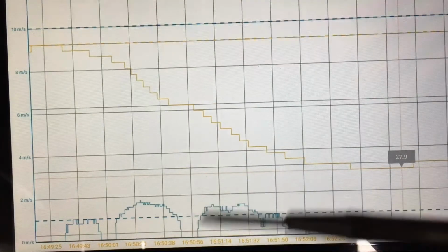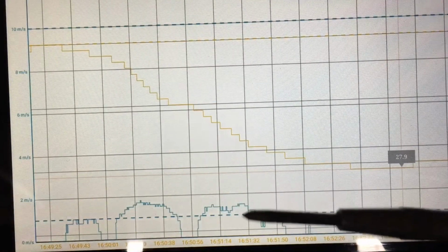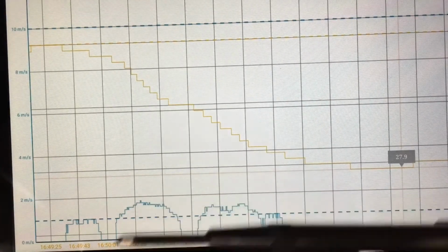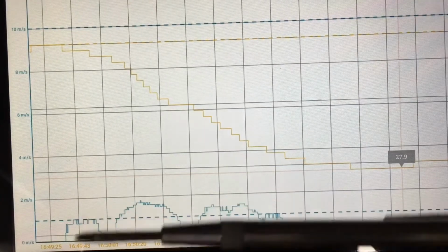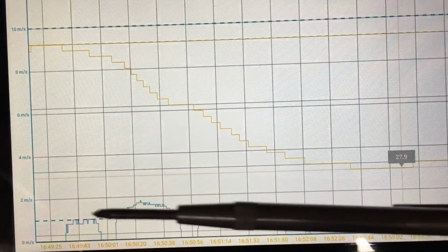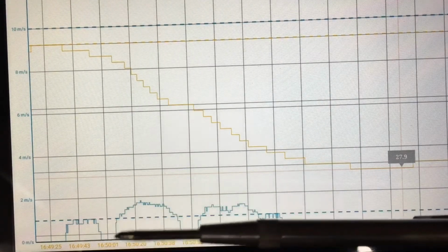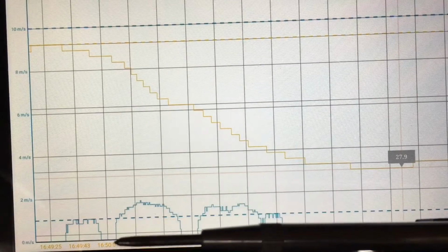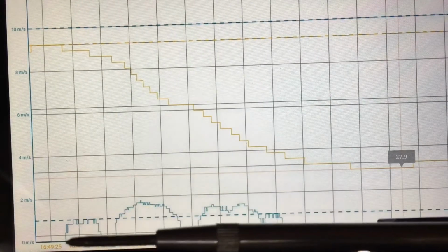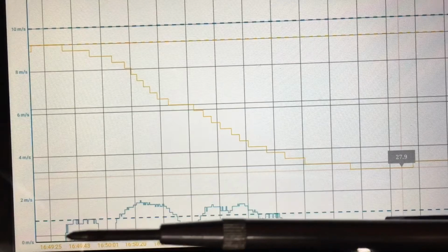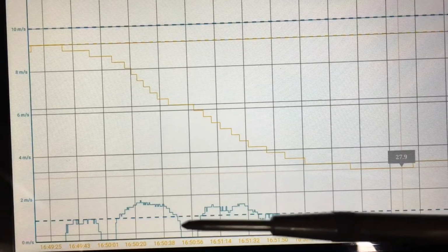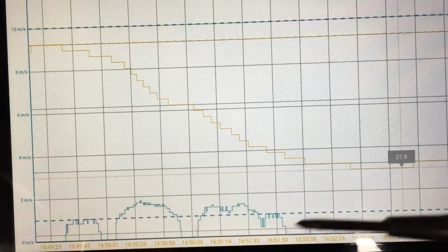Now, this is no rocket science. It's quite intuitive that people would think that, yeah, you're going to have an increase in airflow as the speed of the vehicle increases, but how much? I just wanted to get some sense of how to quantify it. With the little cheap anemometer, you can see there's quite a sharp spike, but the little turbine has to overcome its own inertia before it starts to register. So it didn't start registering until around 50, 60 kilometers an hour, but then on the decline, it continued to register to quite a lower value, is my point.